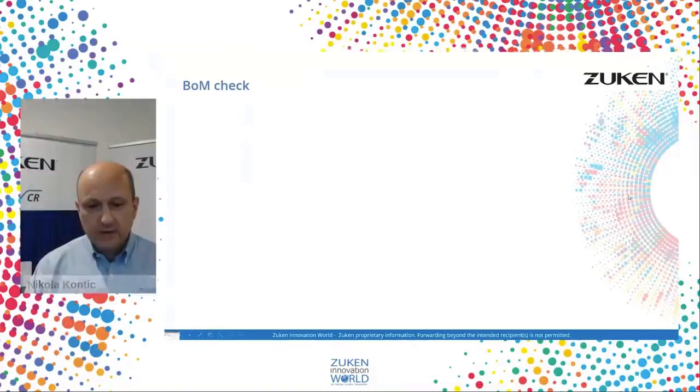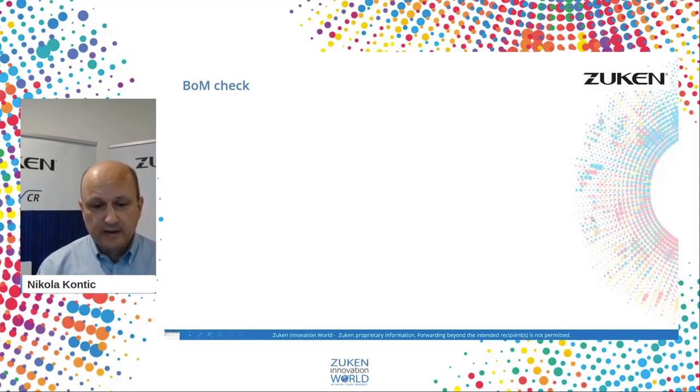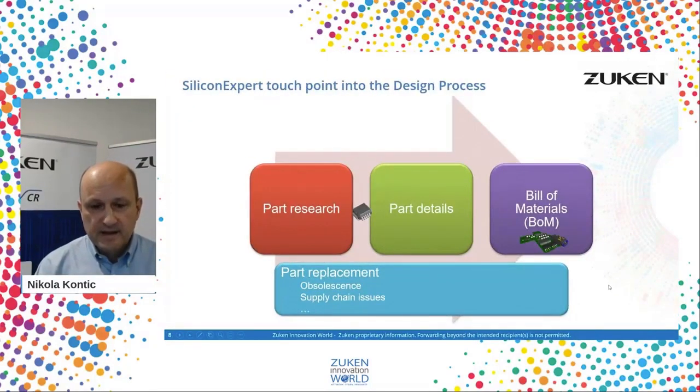So that's showing you how we'll develop our confidence level in the bill of materials, and we're happy to move forward with the product into production, so releasing it and putting it into production itself. So at that point, we have no concerns on obsolescence of the part. We know it's got a good product life cycle. We've seen that the supply chain is readily available from multiple electronic component distributors. The volume is available. We can look at the pricing, we can look at the lead time, and all that has given us the confidence that we should move forward and release this product for manufacture.